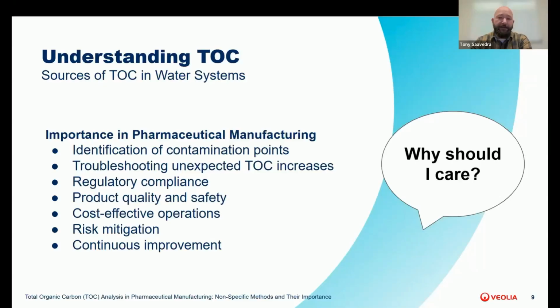Next, with real-time TOC testing, when a TOC spike occurs, you can quickly investigate and take corrective actions, minimizing disruptions to operations. Also, a comprehensive grasp of TOC sources also ensures compliance with regulatory standards, including good manufacturing practices, GMP. This compliance is intrinsically linked to the next bullet point on the screen, product quality and safety. After all, TOC can significantly impact drug stability, efficacy, and safety.